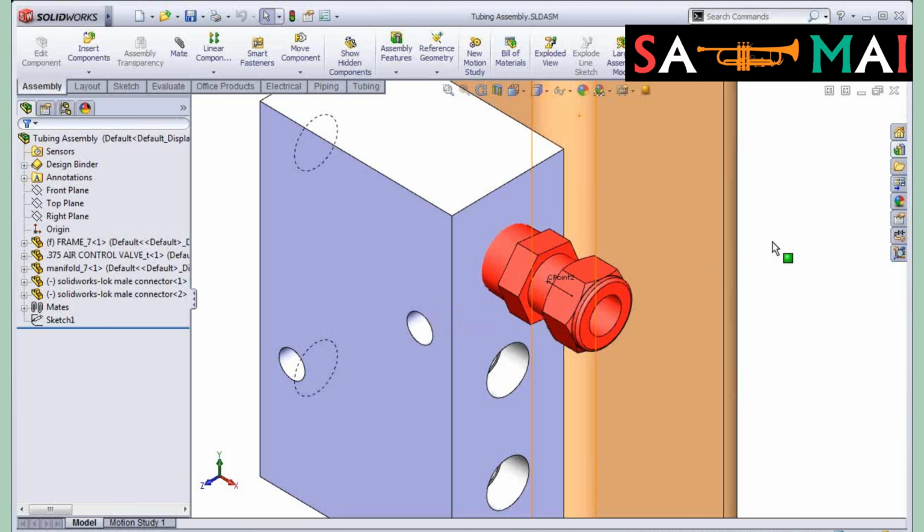All right, the easiest way to do routing is to go to the start and then go to the end and worry about what to put in the middle, rather than drawing and winding up at the middle. So I'm just going to right-click at the start connection point. Now these connection points have a lot of intelligence in them.